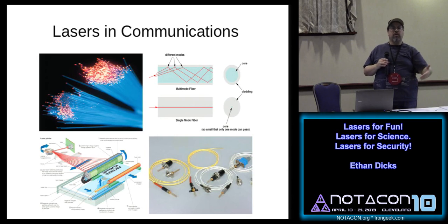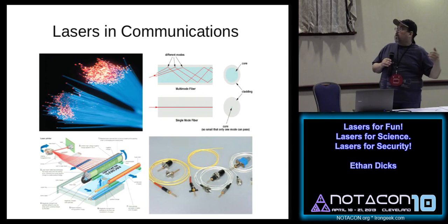You also don't want to waste extra time. You don't want to lose 20 or 30% of your time. So you use single mode fiber, which is harder to build, harder to align, harder to terminate, but you get much more efficient transmission, you get faster transmission, and you see it's a much cleaner looking path.